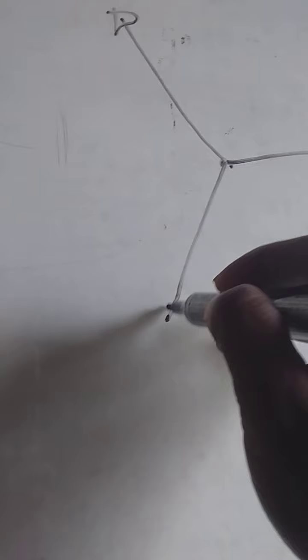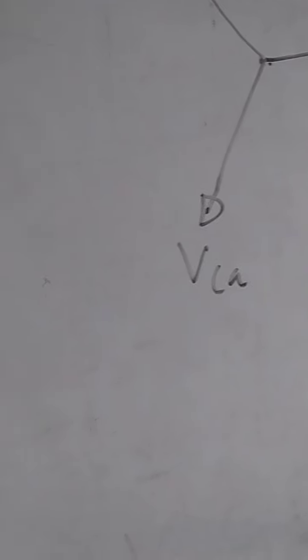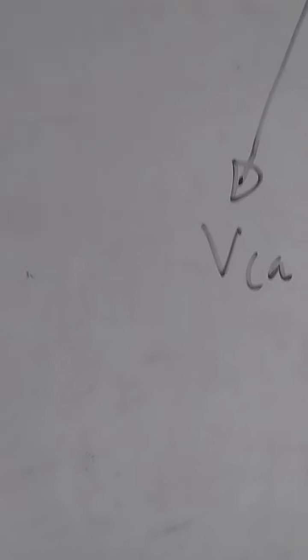Then the next thing is to determine the direction of rotation, which is positive phase sequence. So from here, you are going to have VAB at this angle and VCA at that point. Then from there, you can determine the other phase voltages.